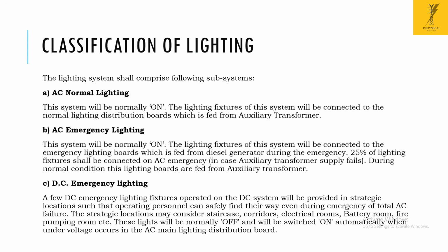You know lux, right? Lux is a measurement of the intensity of light. First, let's see how I am classifying the light illumination in the substation. I have three types of lighting. One is the AC normal lighting, where the system will be normally on. The lighting fixtures will be connected to the normal lighting distribution boards, which are fed from the auxiliary transformer.